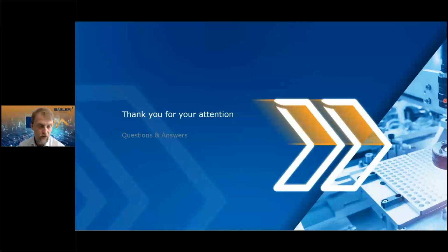Okay, this is a very good question because we don't have frame grabbers for GigE. Doesn't mean that we can't use a frame grabber. We can use the frame grabber as a co-processor device. So even when you have a GigE camera, you can put a frame grabber, even a CoaXPress frame grabber, for example the imaFlex, into your system.